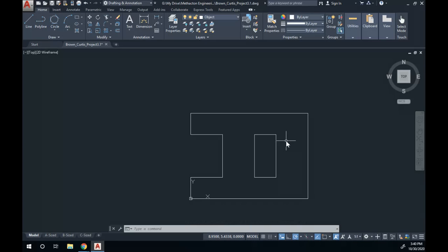Now it's time to draw the circles. I'll draw the top left circle first. It says we're supposed to use a diameter of 1 for that. So I'm going to go to my circle command and hit the drop down key. Make sure I have center, diameter chosen. It says specify the first point. So I'm going to manually input 1, tab, 7. Actually, comma also moves you over. I didn't know that. Something you learn every day. Hit enter. So it locks it into that coordinate point. Then you input the diameter as 1, enter, and it makes that circle.